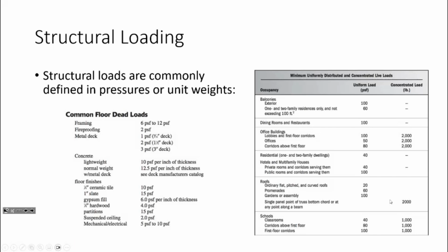On a side note, the floor system in Drinko is actually really interesting. They use a waffle slab, so it's a two-way reinforced concrete slab. So it's a slab and there's ribs that go this way and ribs that go this way, and if you look, it kind of looks like a waffle. Because it's got to hold up a lot of weight. So I don't know, just kind of cool.